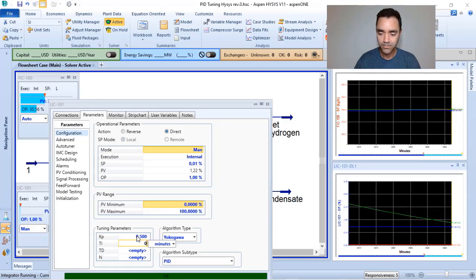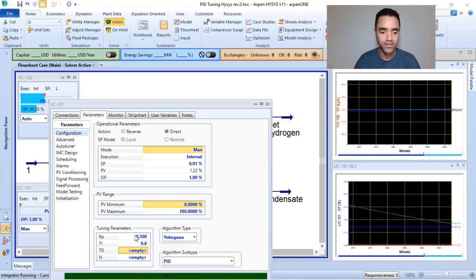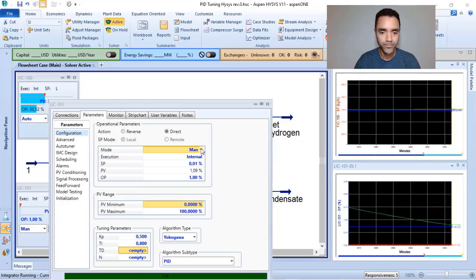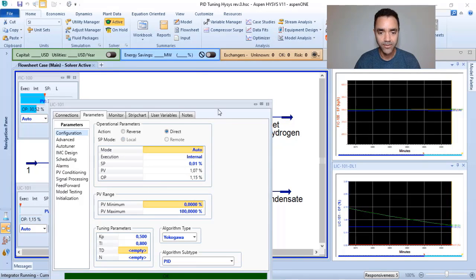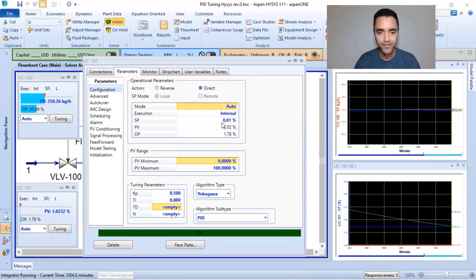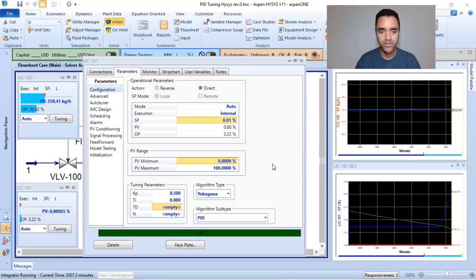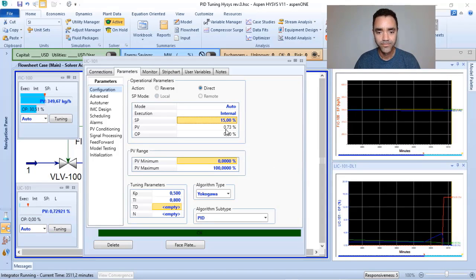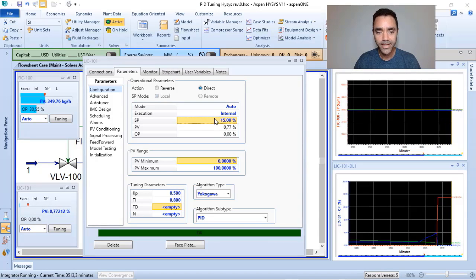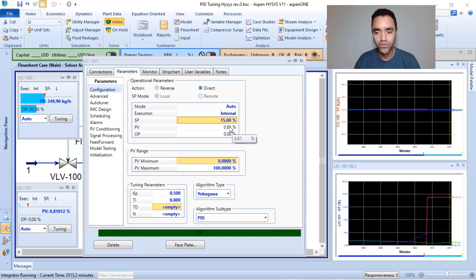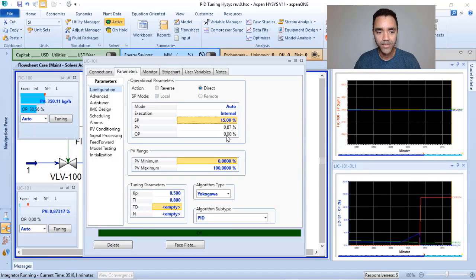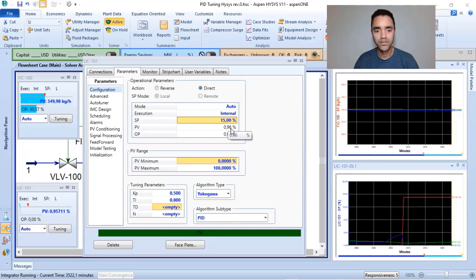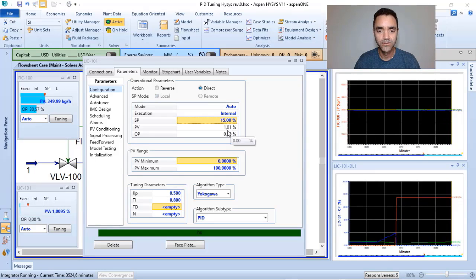So now what I will do, I will go to the settings. Let's define the KP and TI, and let's put it on auto and verify if my system responds. And the set point here was 0, so I want 15%. So as my present value is below the set point, my valve closed, and now it's increasing the PV. The vessel is filling.